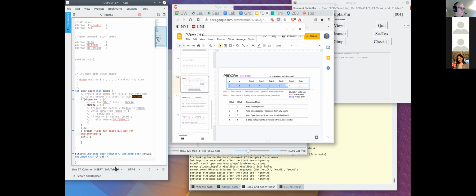And what we're going to do here is define specifically in the set val what bits we want to set. And we're also going to define in the clear val what bits we want to clear. And it can be confusing. Should we use zeros to indicate the bits that we want to clear? Or should we use ones to indicate the bits that we want to clear? So the way I did it is to think about ones for everything. So we're choosing bits by using the ones, but their effect is determined by their name and their position there.